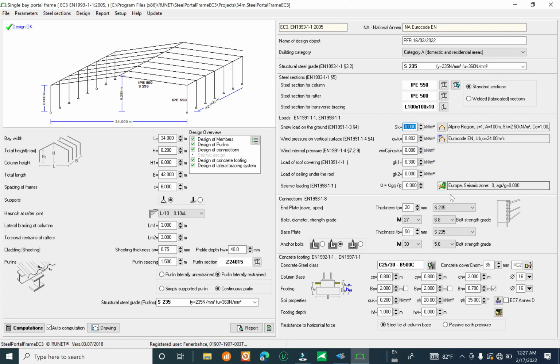Okay, and we have to select the plate thickness, strength of plate, and bolt. Okay, you can select bolt diameter. If you use smaller bolt, we use the large amount of the bolt, but if we want to use fewer, we have to select the larger bolt diameter. Okay, larger bolt diameter. Okay, and we use a high grade for the steel connection. For the bolt connection we use lower grade, and everything here will be automatically calculated.